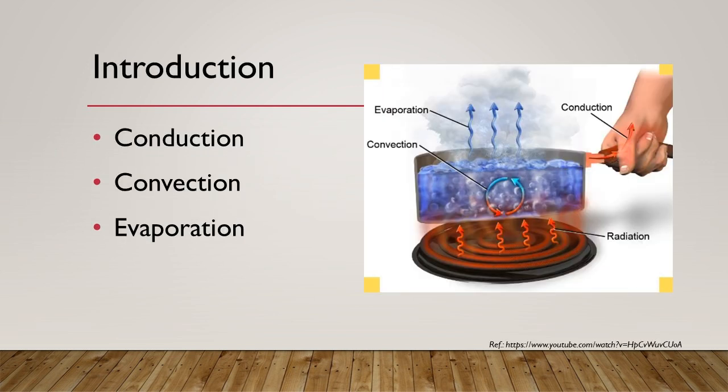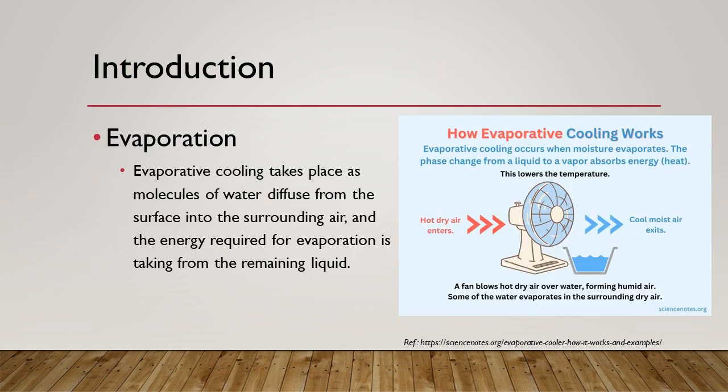Consider the surface of a warm water droplet or film in contact with an air stream. If the water is hotter than the air, it will be cooled by conduction and convection, which will depend on the temperature difference, the contact surface area and air velocity, and by evaporation. Cooling by evaporation is by far the most important effect.